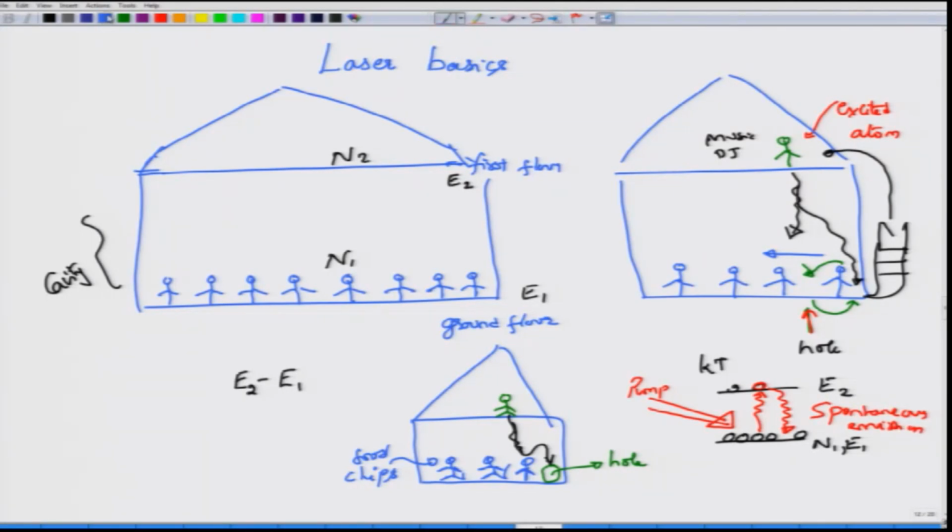There is also another way in which these excited electrons can fall down, when a certain photon or optical packet arrives, of the energy which is just sufficient for the excited electron to drop down. So, it is kind of going there and saying, hey my friend, why do not you drop down. And when it does so, you will actually get two photons, one because the atom has moved from energy state E2 back to the energy state E1, that is, it has combined into the vacant hole here, which releases one photon, and there was already an original photon which was initiating this interaction, which does not get absorbed, it remains as it is.